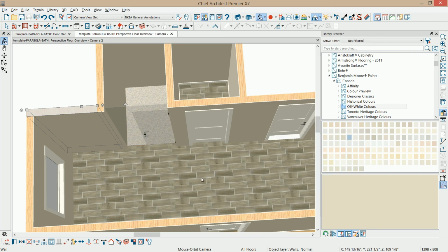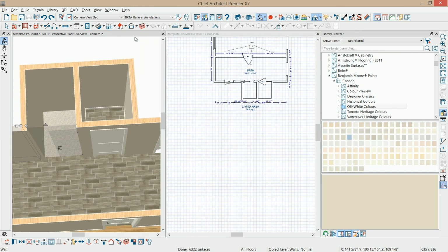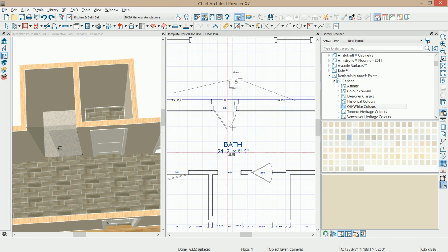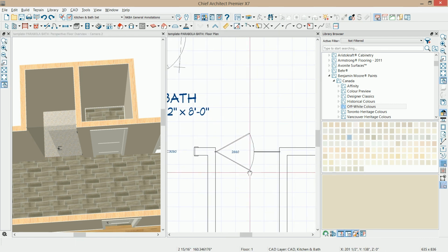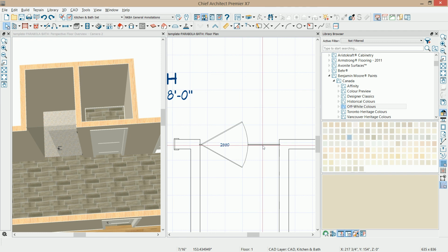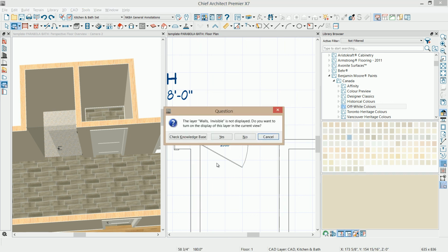So in bathrooms, what I do, let me tile my views by pressing Shift F6 on the keyboard. And I'll just zoom in. You'll notice my glass shower wall is set back a little bit. To save time, I'm going to use a room divider tool, which is made to set up room definition. And I'm just going to come in here and create a room division.